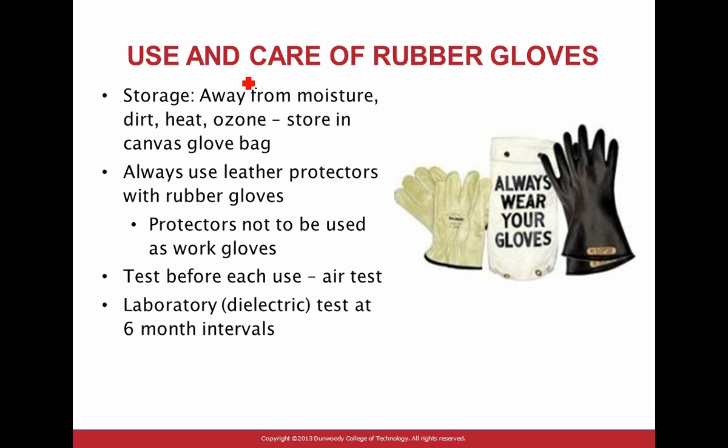Okay, use and care of rubbers. A couple of things about the rubber gloves. For storage, you have to store them away from moisture, otherwise you damage them, and dirt and heat and whatnot. And always use a leather protector. Remember, the rubber will protect you from shock, and this one is to protect. So your leather protector with rubber gloves, you have the combination of the two, basically. And that's why we use these two together. One for shock, one for arc flash.